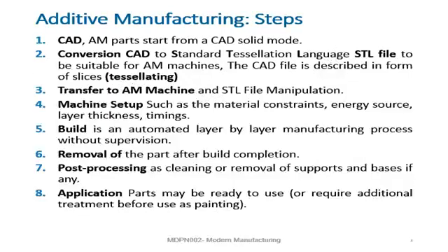What are the basic steps in additive manufacturing? The first and most important step is to have a computer-aided design solid model, a three-dimensional model of the part. This virtual model is converted into another type of file, known as a standard tessellation language file, which takes the three-dimensional model and changes it into slices.